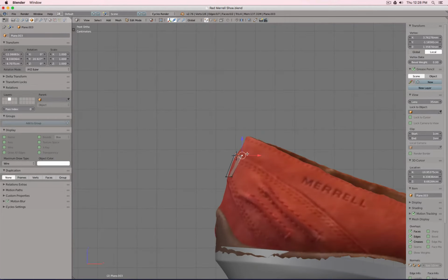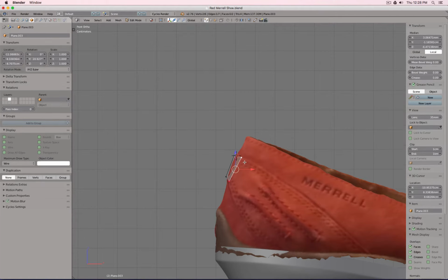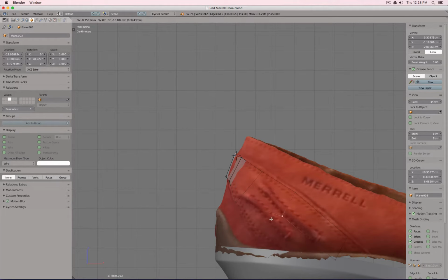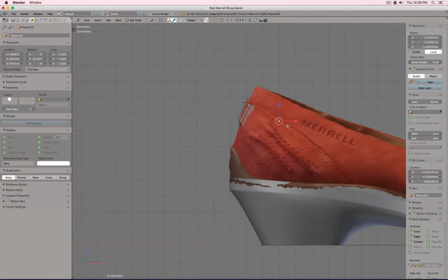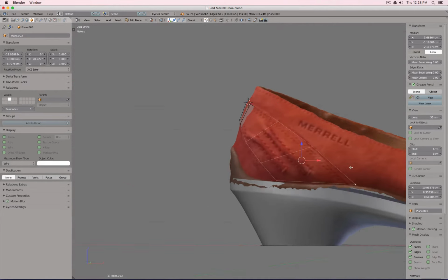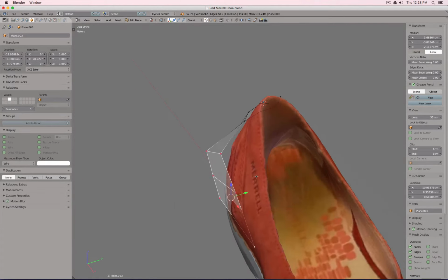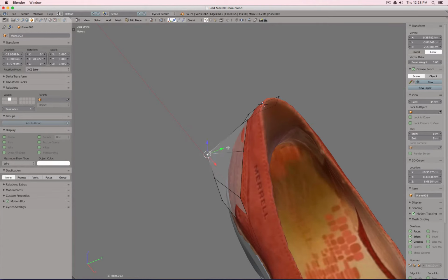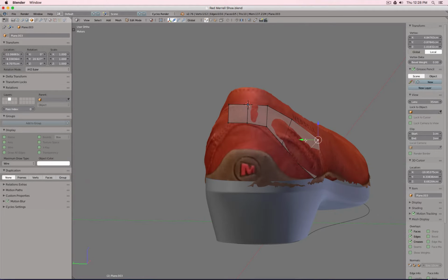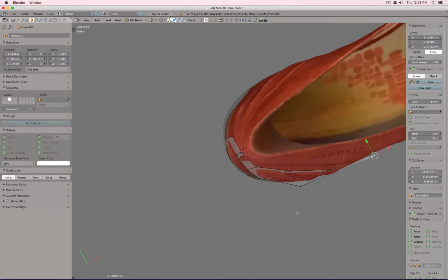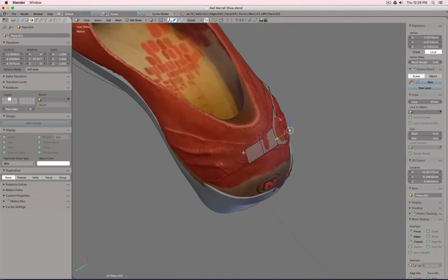Now this will be a little bit of modeling work. So from this view, 1, 2, and 3, there and there. This one maybe to there, this one maybe to there, this one maybe to there and there. Just have to fan those out a little bit. Okay, and then also from here, let's move those out to there and there. Try to do this step rather coarse. Try not to be too precise, because the moment we add the subdivision, this actually will get softer again.